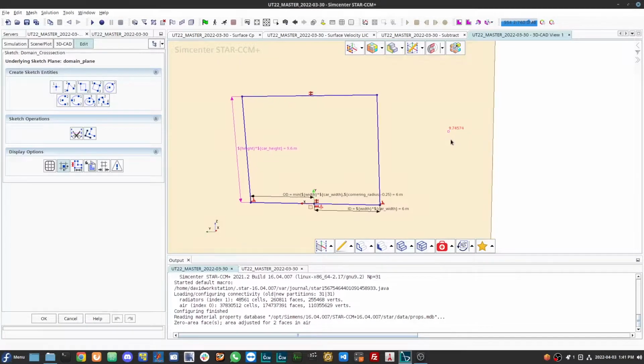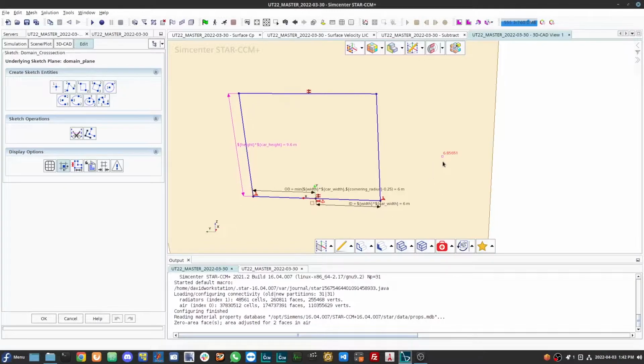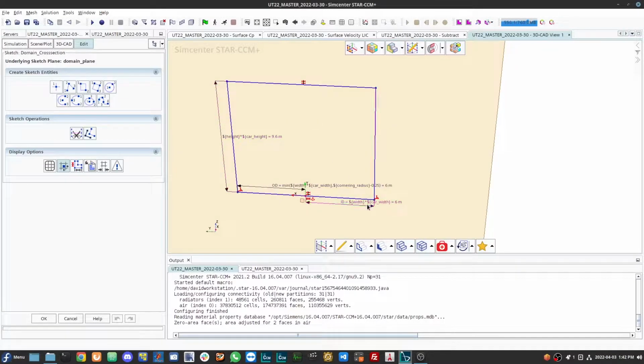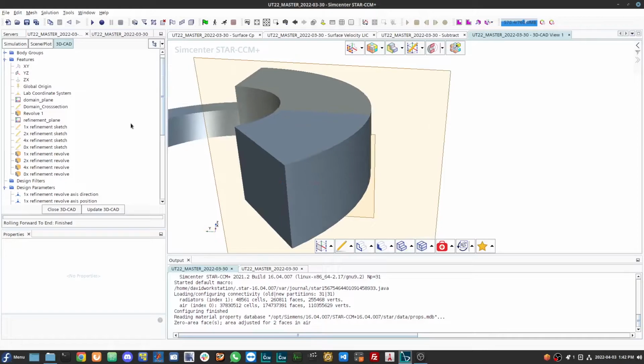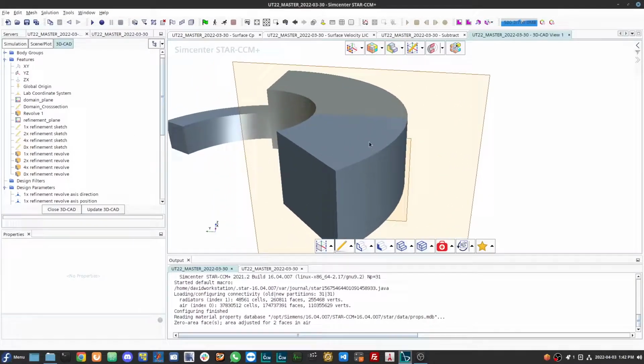And while not shown here, what you can also do is, using an if statement, set one of these values to 0 if you have a symmetry value set to 1. And that will just cut off half the domain and will give you a symmetry simulation. Now you might be saying, it's a cornering simulation, you can't really do symmetry. Well, if you set the radius to some absurdly high number, like say 500 meters, it's effectively going to be a straight line simulation with some of the relative flow angles maybe about 1/3 of a degree off, an acceptable sacrifice for ease of use.